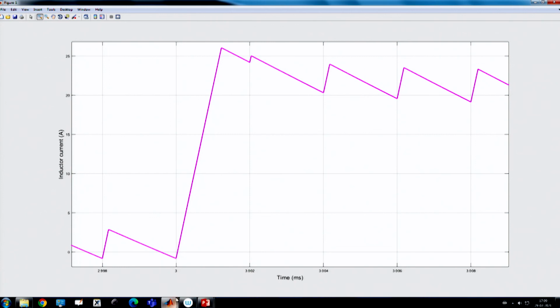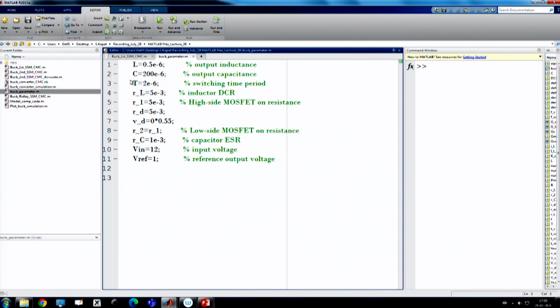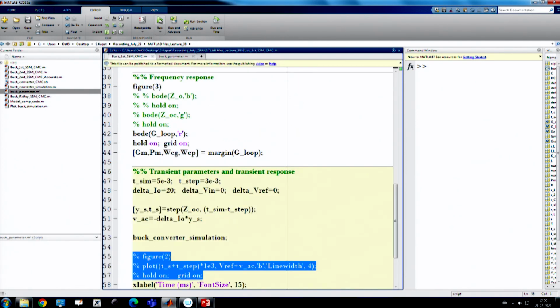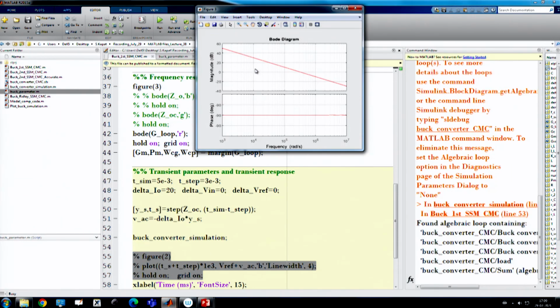So, if you go back to our power stage design, if I reduce my inductor value, that means if I go to my buck converter parameter and take a smaller inductor, let us say I am just taking 0.1, the ripple will be quite large, but let us say if we run it at 50 kilohertz, then you will see the output has almost no effect, right.